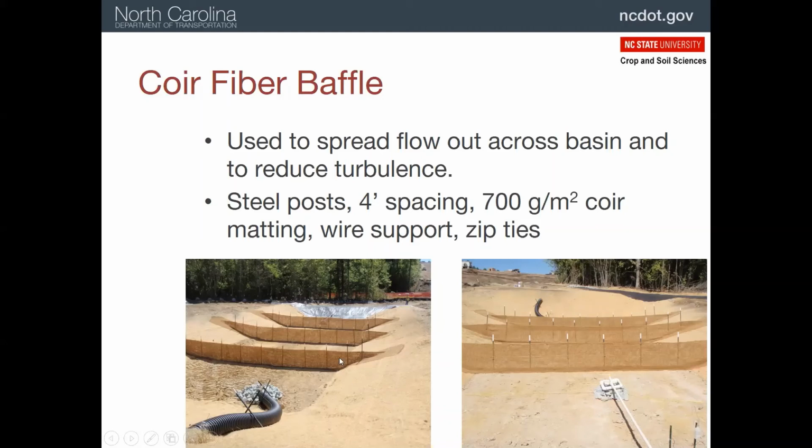And then we have the baffles, 3 of them evenly spaced. And then we go to the other end and we see our Faircloth skimmer that's been installed on top of a rock pad. And in this case, they put rope on both sides of it, probably to keep it from floating to the side and keep it on that rock pad. So this is what every skimmer basin should look like. Just kind of remember that. Okay, so now back to the baffles.